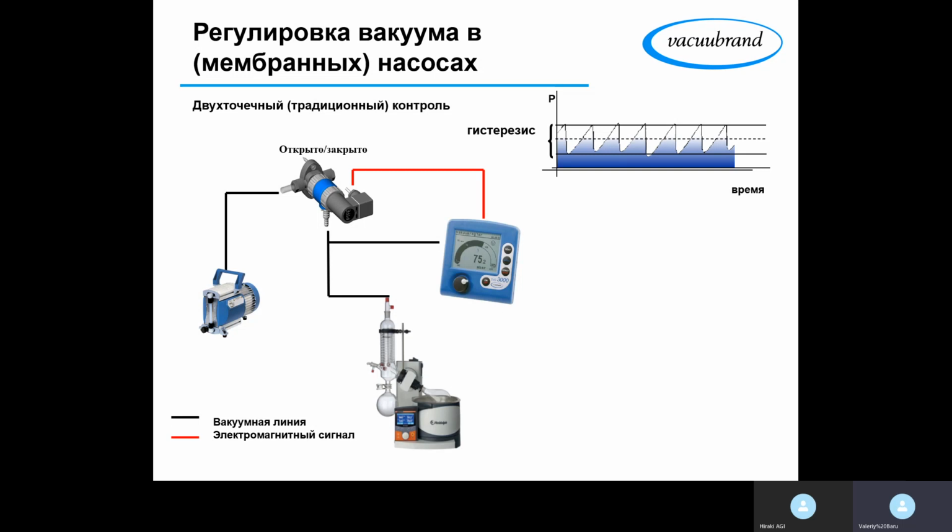If I'm not mistaken, for a standard rotary evaporator, the standard surface is about 1,200 square centimeters. And in this case, we can have safe evaporating with a performance of about 1 liter of water per hour. Roughly like this. These figures are in the catalogs, so you can easily get them from there.